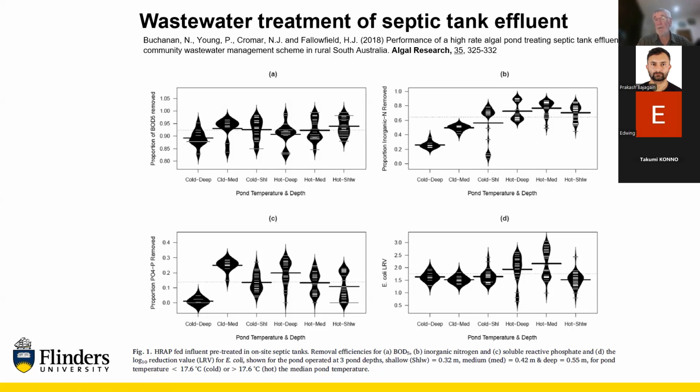Engineering depth changes. We could do this quite easily, but a lot of the engineering design is quite novel about how we do this. But designing and having an operational manual that says change the depth of the pond, in our case, winter would be July. Change the depth of the pond in July and operate at 0.32 meters deep. Is there advantage to that for a very short period of time? To complicate operation? Probably not, in my view. So we tend to operate constant depth ponds. Is that okay? Is that clear?